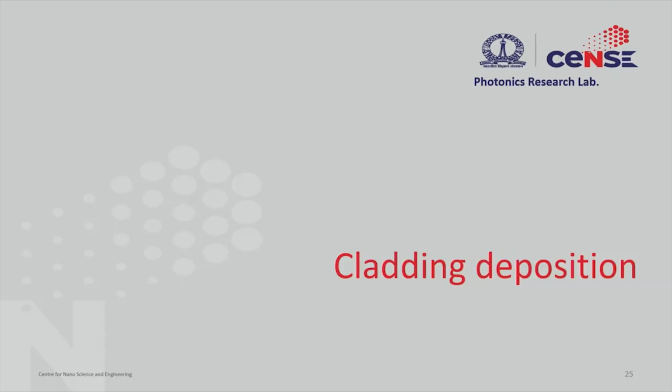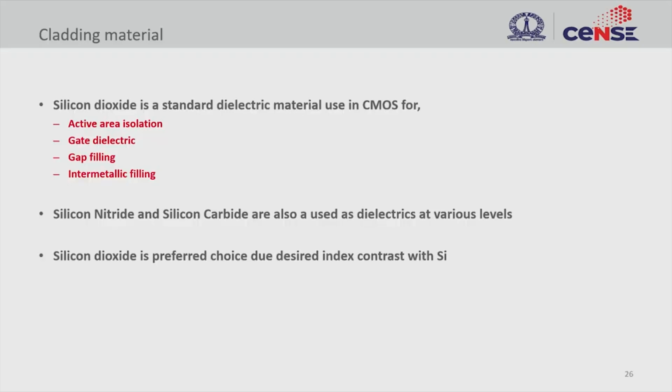The next important thing is cladding, right? So you put a coating on top of your device in order to protect the device. Normally silicon dioxide is used as a typical cladding or coating material, and this is used in multiple places, right? Active area isolation, gate dielectric, gap filling, and intermetallic filling. All these places we use silicon dioxide.